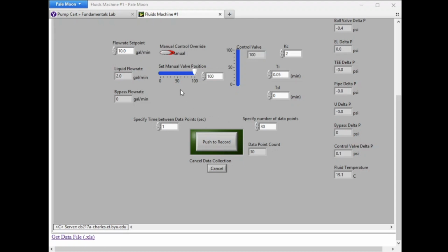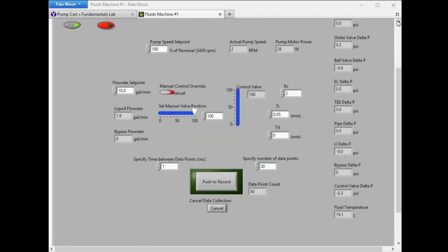And then you can see for these others, I'm going to go ahead and do maybe 6 runs, one at 0, one at 12, one at 25, one at 50, one at 75, and one at 100. Actually, let's do 0, 10, 20, 40, 60, 80, and 100. We'll skip 10. 0, 20, 40, 60, 80, and 100. That'll be good. So we'll come down here and set it directly to 80. And then we will turn the pump back on.